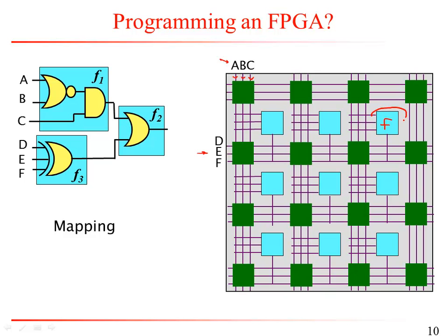If I give you a 3-input function, and I give you a ROM which has 3 address lines and 8 bits in the ROM, you can basically put the Boolean truth table of that function into these 8 addresses of the ROM and use the 3 inputs as the address lines, and the output would tell you which one of the bits is going to come out. That's essentially what FPGAs do. That's how they implement logic.